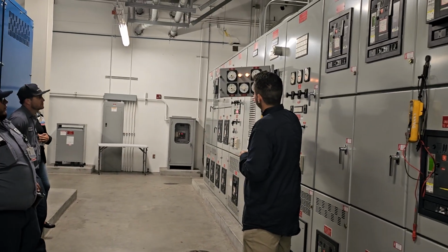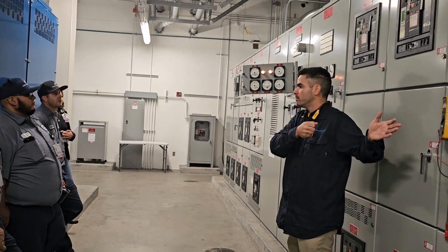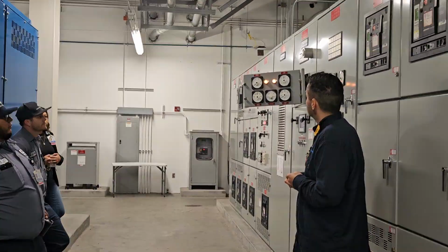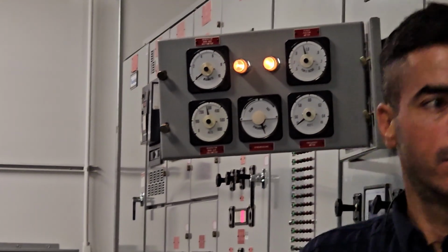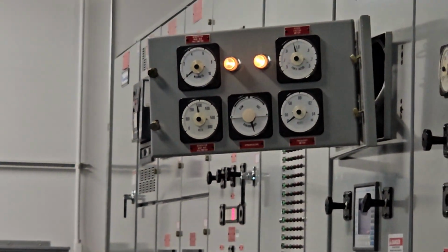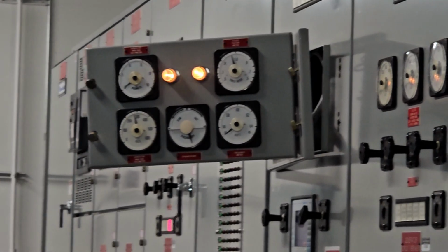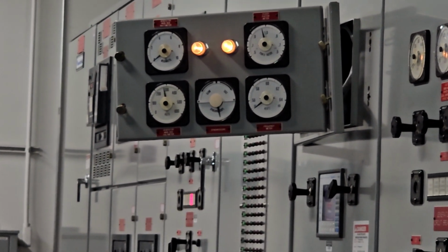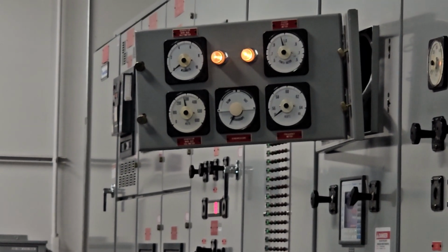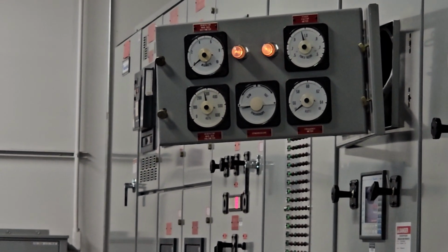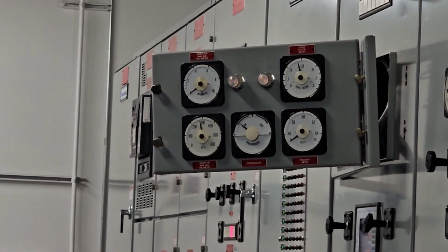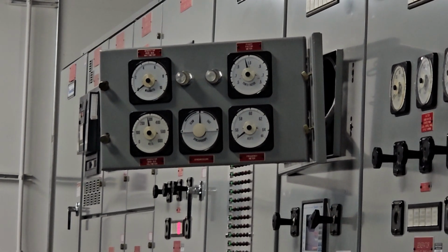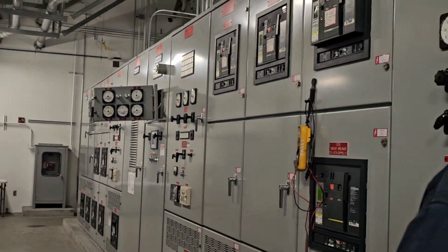Right now it's at 6 o'clock, so if the system lets me attempt closing, it will be bad, right? So if you guys are under this condition and it's super important to bring the second gen online, you can move the frequency a little bit for this guy, and look how that goes faster. You see? Now when I get to 12, look, the lights are turning off, and I close the breaker. Right at 12, I attempt to close it, and now it stays closed, right?